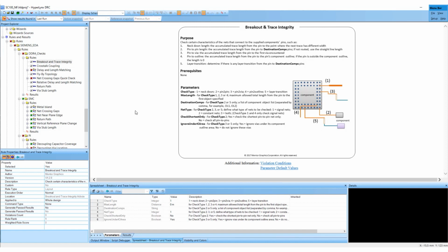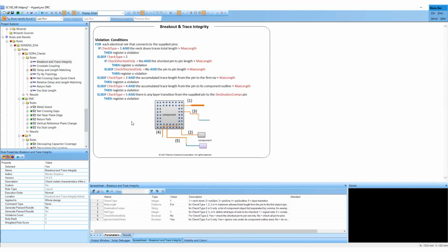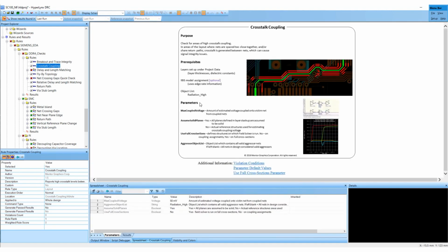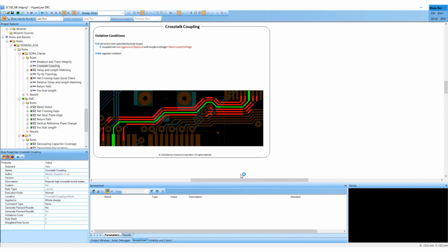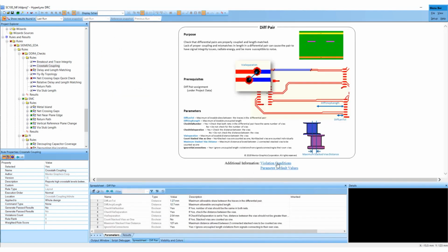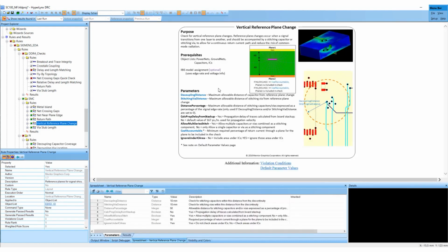By left shifting some of this simulation to earlier in the PCB design cycle like Wilfred demonstrated, we aren't doing one final electrical sign-off at the end of the PCB design cycle. If we only simulated at the end of the PCB design, potentially catching a layout error could be disastrous. Having to go back, move placement, rip up routes, rework the board, and start all over, and then simulate again at the end of that PCB design. By investing in automated simulation up front and checking and correcting as we go, we save ourselves a lot more time and money down the road. This helps our hardware designers meet their design cycle reduction goals.